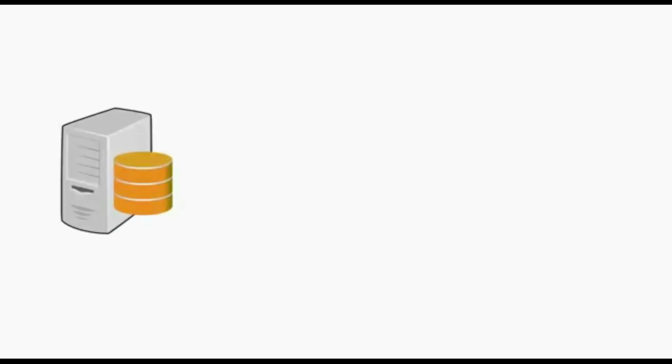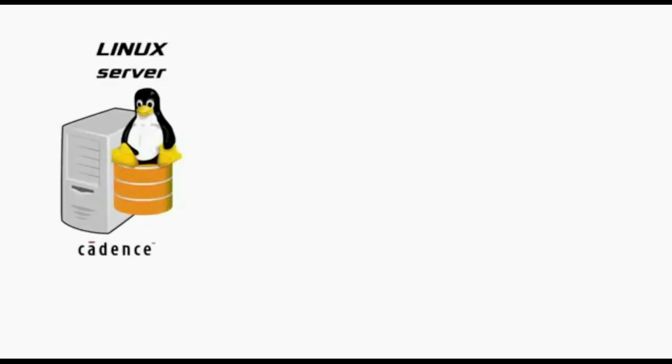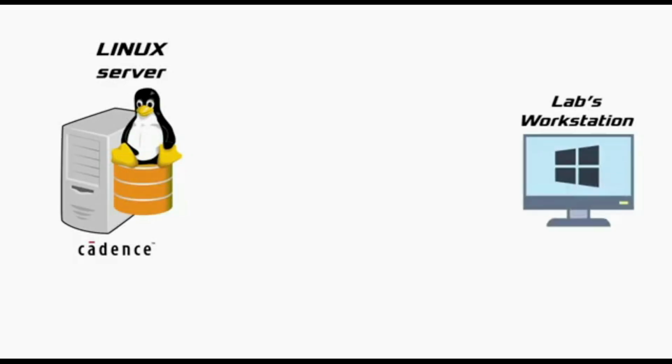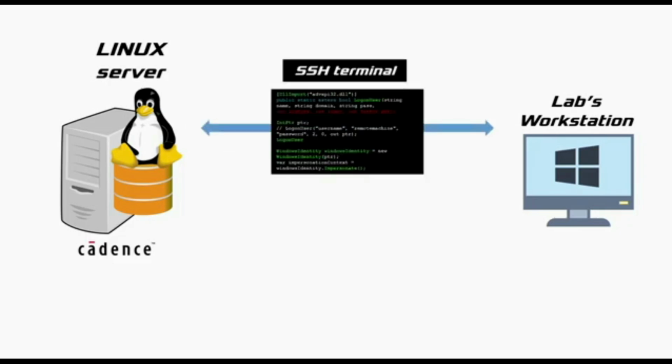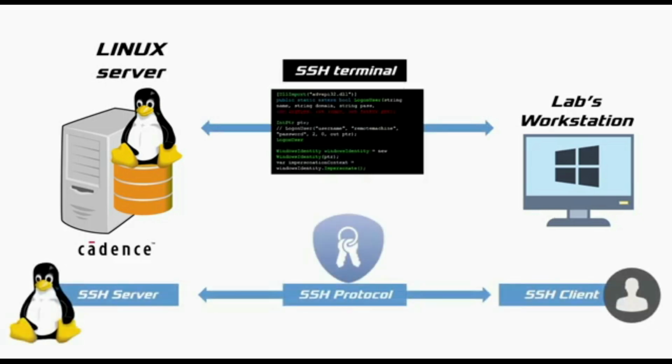multiple domains. The fact is, Cadence does not run in Windows because most of the Cadence tools are Linux based and run on a server. Usually, users need to log into the Linux server to initiate Cadence from their workstation, and the Linux server can be accessed through any remote login client tool through the SSH network protocol, like shown in the figure.